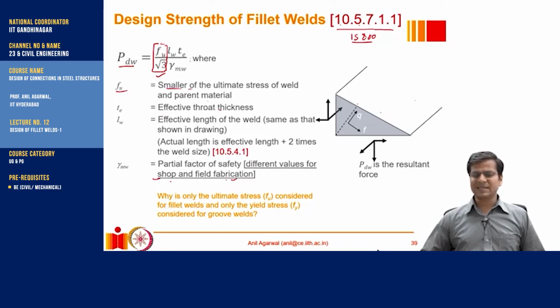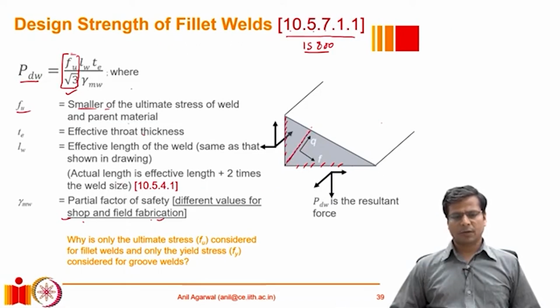Whatever types of forces are acting here will be resisted by the other boundary. All those forces have to pass through this interface, so let us design this interface as if it is acting under shear, calculate how much strength it has in shear, and say that that is its strength for whatever forces you are applying.